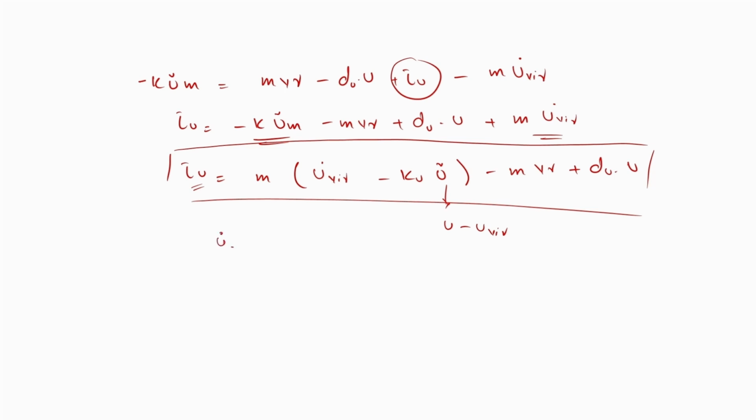If you remember, we had some function f of u plus tau u. So we have achieved this tau u, and when we put this control in this dynamics, we will be able to control u dot. And what will happen with this u control is that we will achieve u approaching u virtual, because this u virtual appears in the kinematics x dot and y dot, and our goal is to achieve position control. Okay, so now we will follow the same steps for the yaw angle control and derive the controller tau r. So let's move ahead.